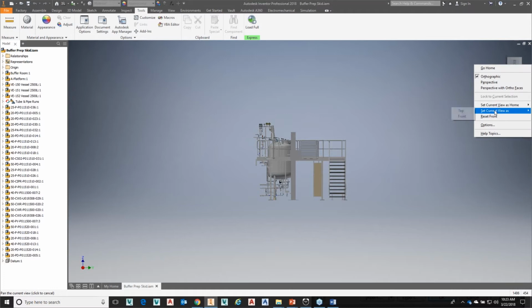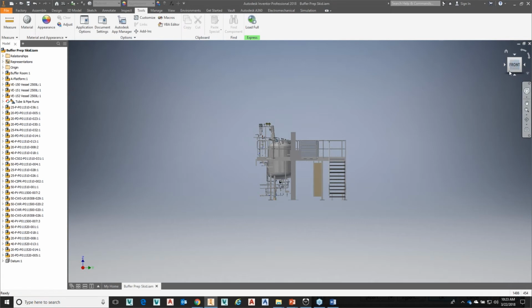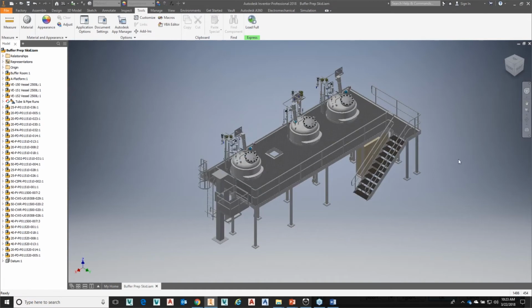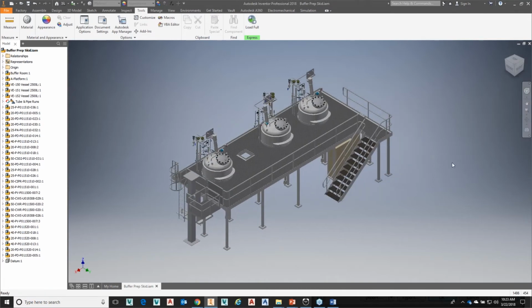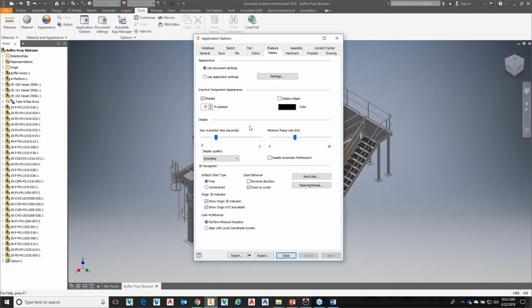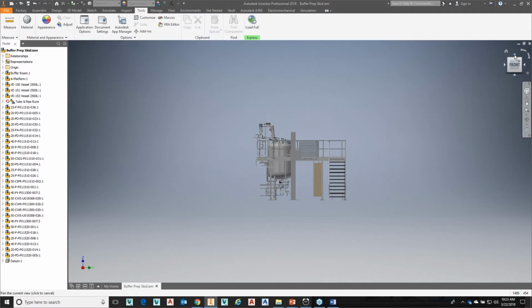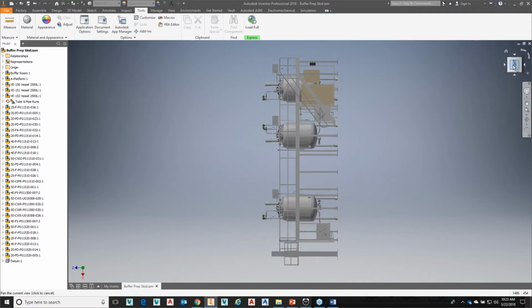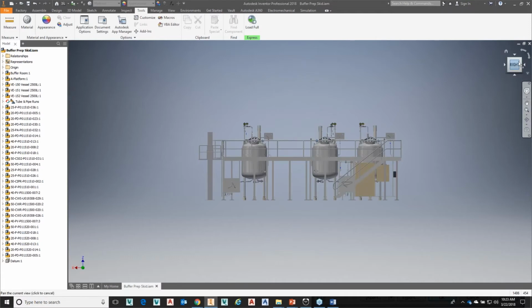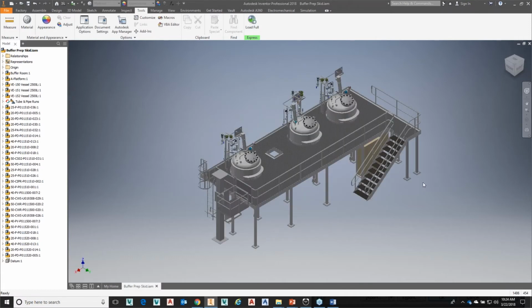So I'm going to change my view cube. I'm going to call this the front, and everything else is relative to that. So this is the front, up here's the top, right side, and so on. And so if I go back to this, you can see this now, okay? And let's change that setting, okay? So view transition, if I set it to 0, or at least slow it down, right? It's immediate, okay? I can get to the top, I can get to the right side, and I can rotate my view accordingly, okay?